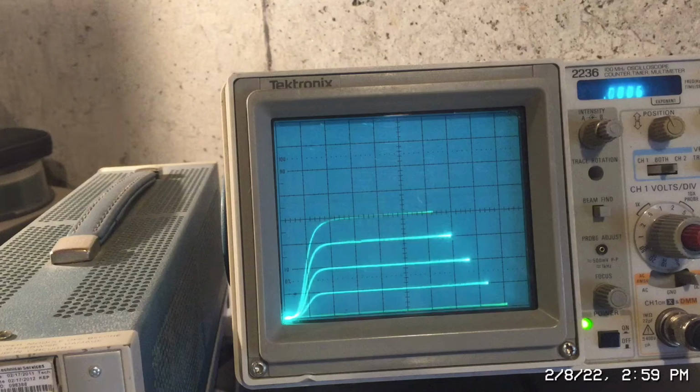So what you can do here is you can just basically sample the collector characteristic curves and match two transistors that have a similar gain. And actually the first two transistors that I measured were pretty good. Okay, so now I've got the baseline Fairchild transistor, and we're going to take a look at the Motorola.